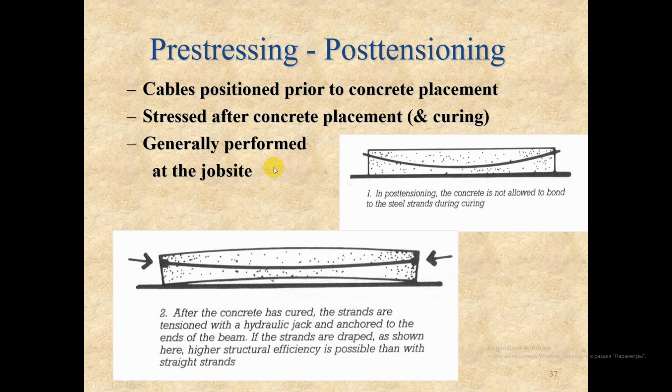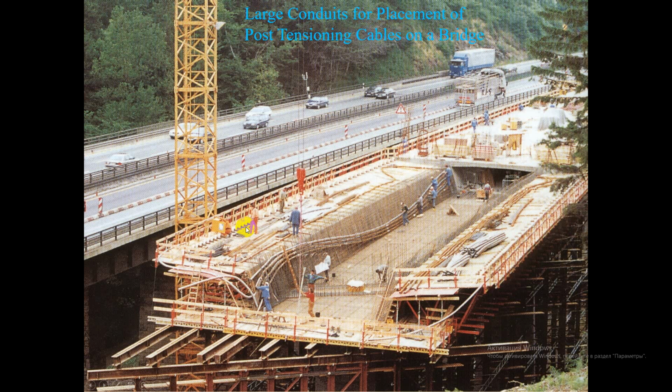Cable positioned prior to concrete placement. Stressed after concrete placement and curing, and generally performed at the job site. Here you can see large conduits for placement of post-tensioning cables on a bridge.